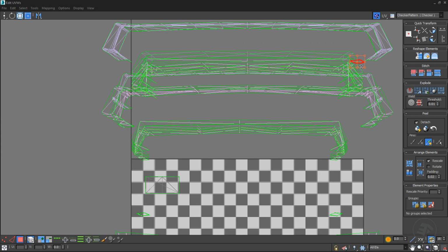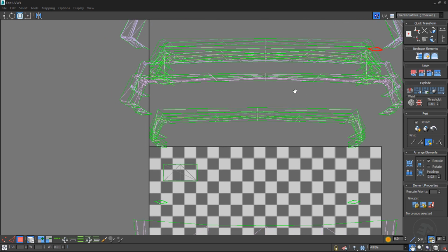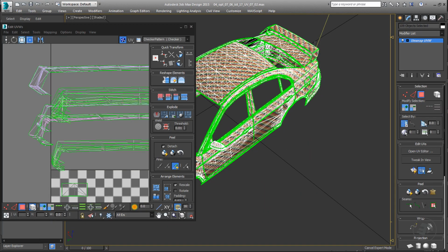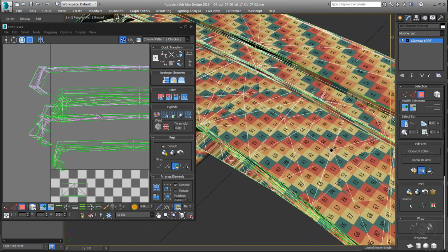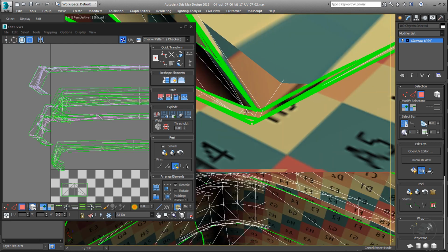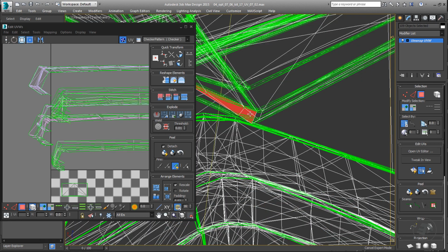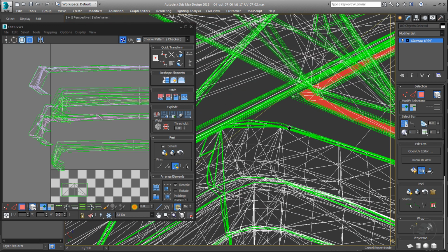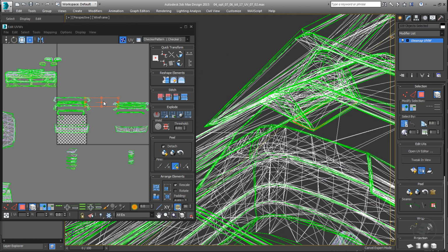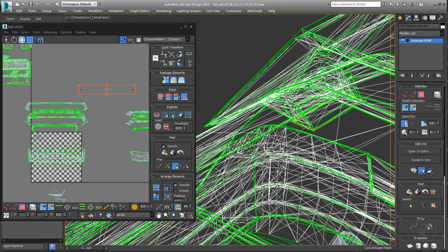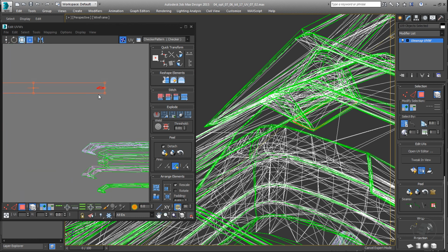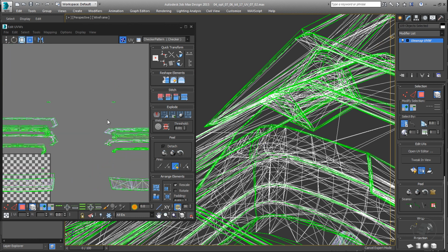We have some UVs that were unwrapped incorrectly. These UVs belong to the top side. For a successful unwrapping process, no UVs should be left behind or have the wrong perspective projection. Otherwise, serious texturing faults might occur, especially when those UVs are on the first level of detail.